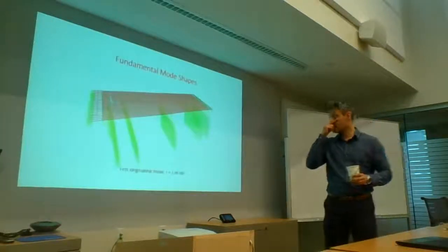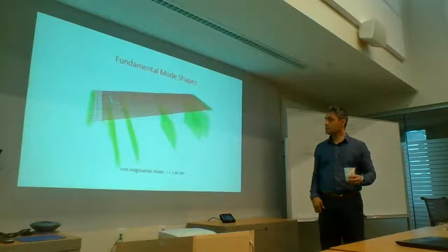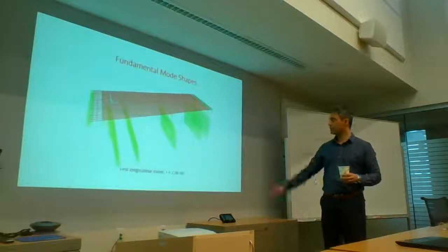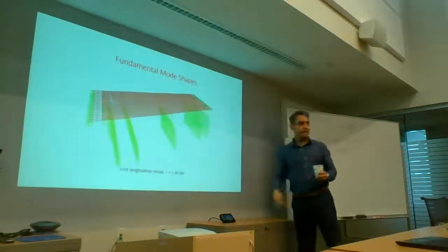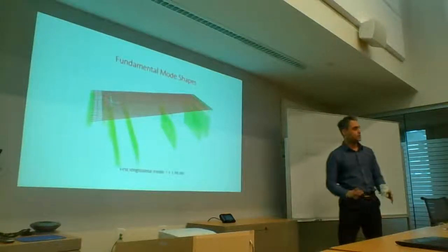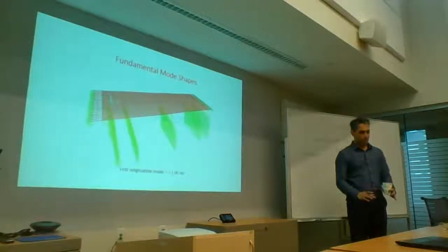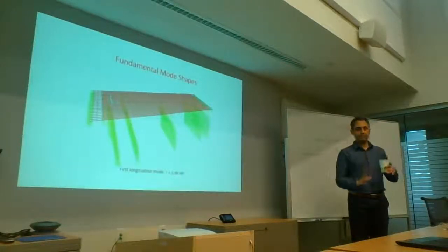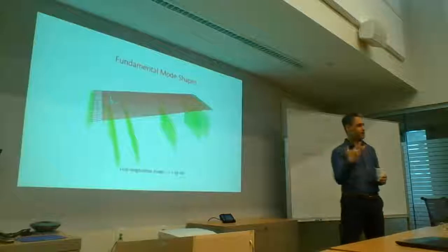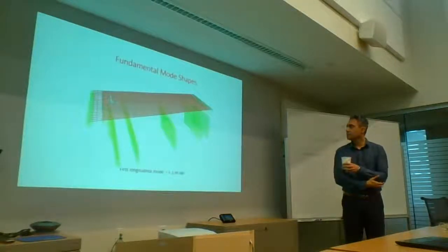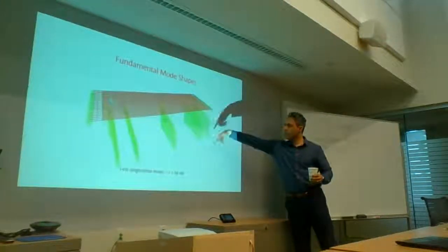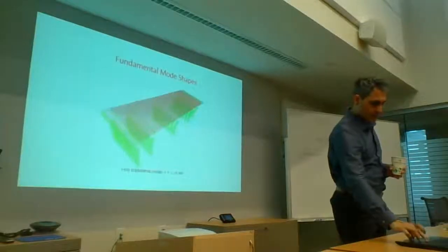This was the model that he came up with. Here the deck was quite wide, so I think he did a grillage model rather than just a stick model to capture any of the torsional effects. These are what we call extended pile bents. The piles are in the ground. They're steel pipe piles that have reinforced concrete in them. Then as they come up and out of the surface, it's just the concrete that's continued up into the air, so that you don't see that brown, greasy look of steel. These are extended pile bents, and from out of the ground, you've got all the PY curves in there. So that's just a little bit of stuff.